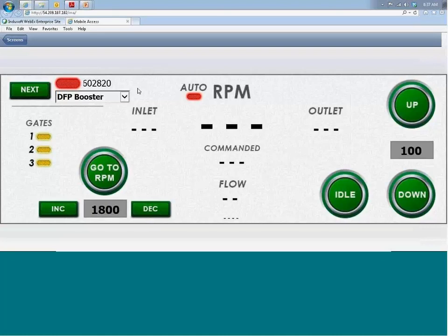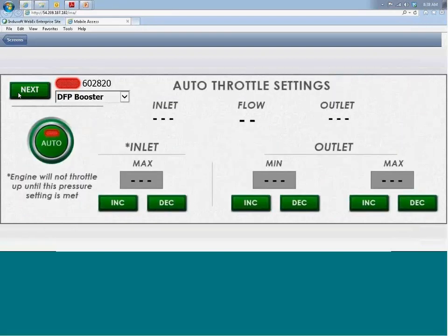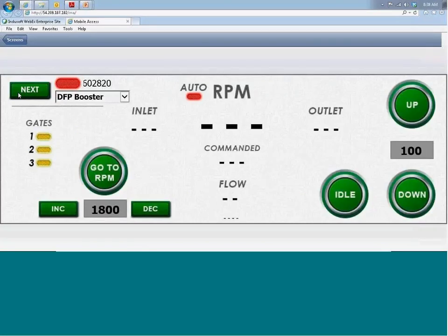and the driver running on InduSoft Web Studio on the cloud automatically receives all those messages from each one of the RTUs, recognizes the RTUs, and automatically makes those RTUs available for the web browsers, for the web thin clients. So there is no polling from the server to the RTUs. The RTUs themselves take the initiative to send unsolicited messages to the server when there is new data to be displayed, and the server simply stores this data and makes it available to remote web browsers when remote users log in to the system.